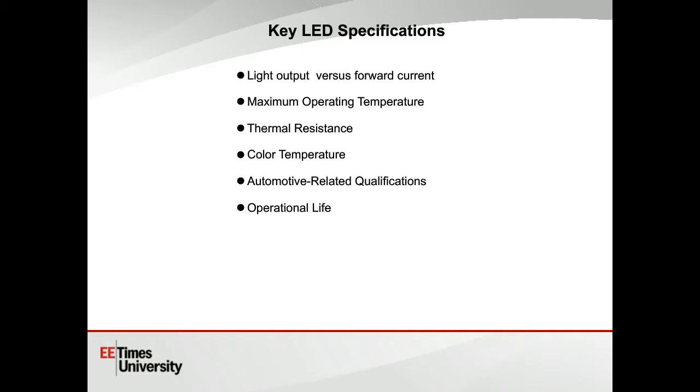For an LED, and again for any semiconductor device, the total thermal resistance is not just a function of the semiconductor itself. It includes each individual component within the IC, such as the package, which is the big one, the leads, even the epoxy, and the bond wires, and so on. So all of those are included, and it's an additive function. All of those are included in the total thermal resistance of the device. For an LED, 1 degree C per watt is a typical number you can use just to give you an idea of what we're talking about.